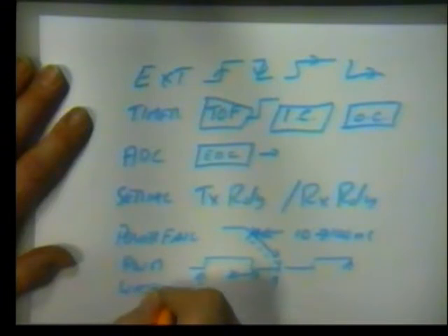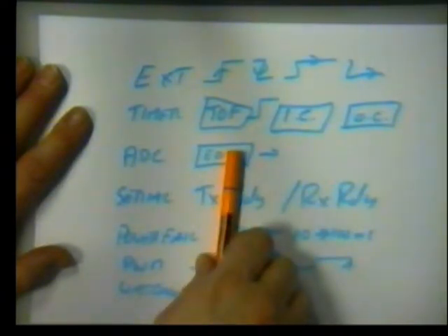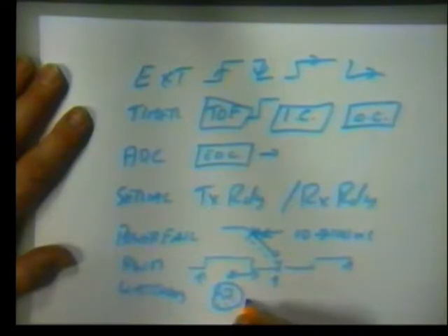Watchdog. So we have a little internal timer, and unless we reset it inside our software, it will eventually time out, and that will issue a reset to restart the processor. There are others. You can pick up a book and you'll find there are lots and lots and lots of interrupts.